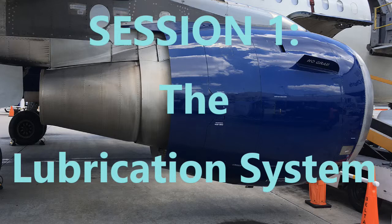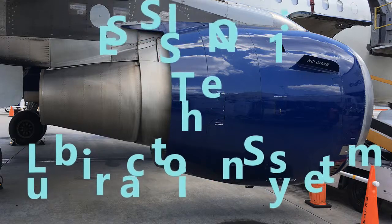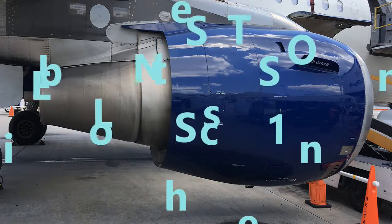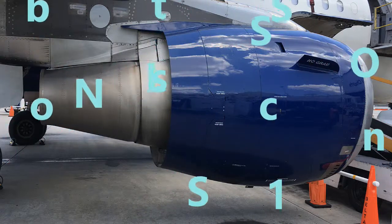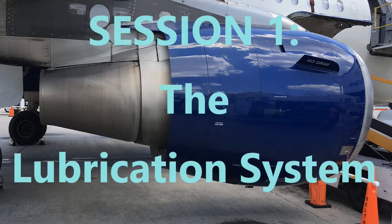Okay. The details as far as the filters. There's different kinds of filters that are used. Just know that there are different ones. Make sure you do pay attention to the serial numbers, obviously, on them when you're switching them out, because some of them look very much alike, and you might mistake one for another, and it's not really the same. The reason why is because they're rated differently, right? I mean, you probably know that, but there are so many different ratings in microns for these filters. And again, they look the same. There's a filter, but what is it rated? So you want to make sure that you're replacing like for like, not by visual, but by serial number.